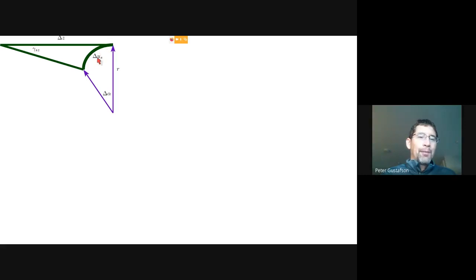In the S direction, I'm going to define an arc length. Basically, you can think of this as being a displacement in the tangent normal coordinate system where it is all tangent. So we're going to call that value US. Okay, so in fact, for any given delta Z, any length delta Z, and we can shrink that length down as we move, we see the shear strain is given by the angle gamma SZ. Shear strains, of course, we can interpret as angles. And of course, at any point in the cross-section, from the center of twist, we're rotating around that center of twist. And the amount we rotate is going to be given in displacement terms of delta US. So this is a tangent displacement that corresponds with a differential length in the Z direction.